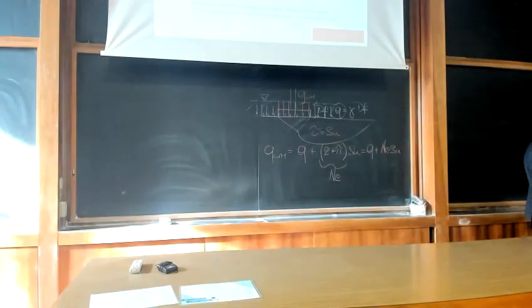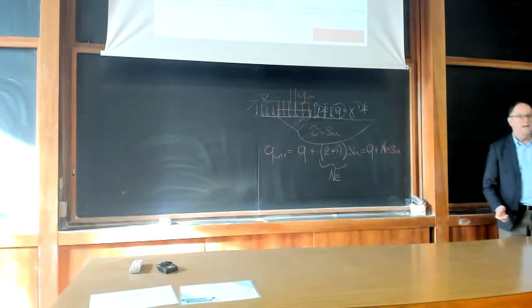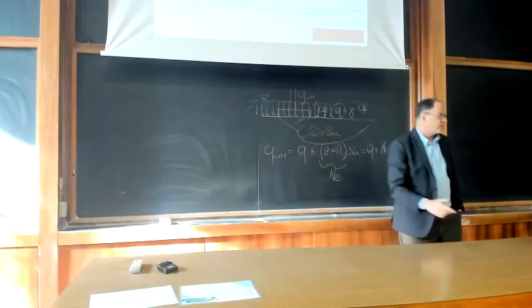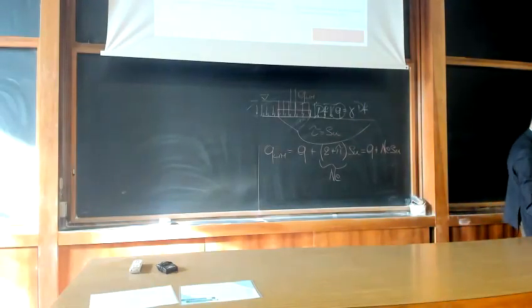Now, of course, you also have drained conditions, and in drained conditions, which are reminded here, we can see that these are drained conditions because you have no pore pressure development. You see that your pore pressure stays constant, and so you develop settlements at the same time as you increase your load.